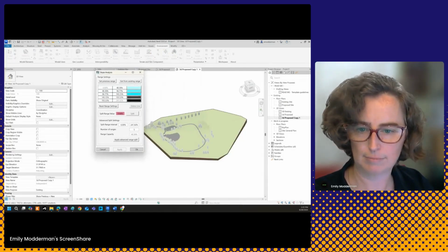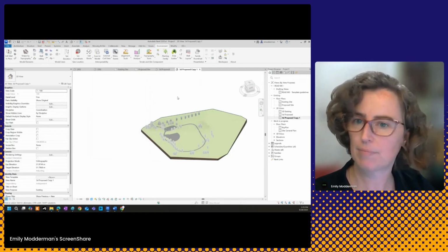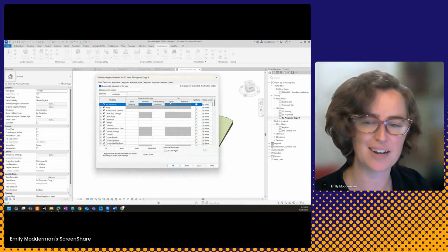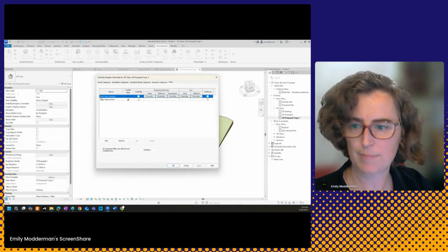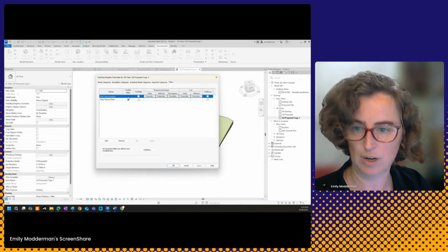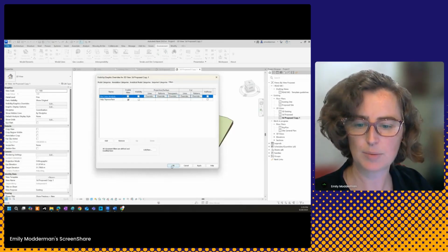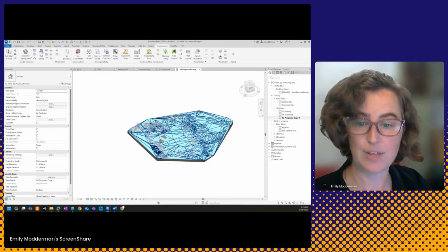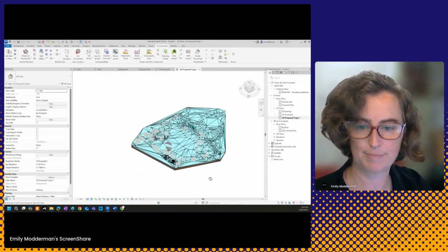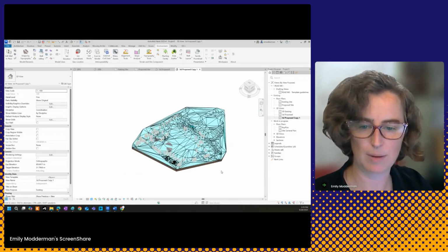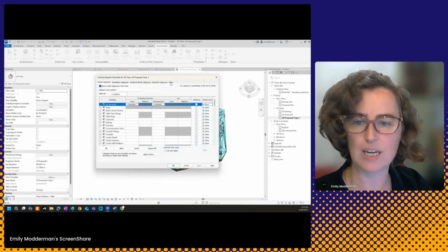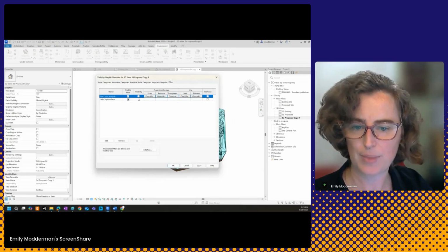and click OK, nothing happens. I always forget. In this particular template, there's a filter on, and it helps to hide that filter or this analysis in views that I don't need to see it. But clearly I want to see it in this view, and that's what I'm going to turn on. So I just went to VV and I turned on my filter.